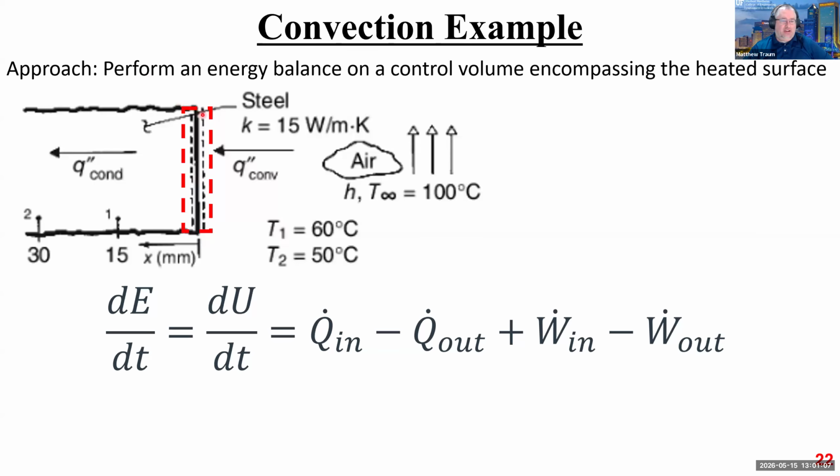So I've got my energy balance, right? So here's the energy balance. This is my control volume. I've got a control surface just upstream and a control surface just downstream of where this multimodal heat transfer occurs. And I've drawn this again with exaggerated thickness, but it is not thick enough to encompass any mass. It's just right there at the surface, no mass. So it cannot support any energy, holding on to energy. Trying to think of the term for that, having a senior moment. So it can't hold energy.